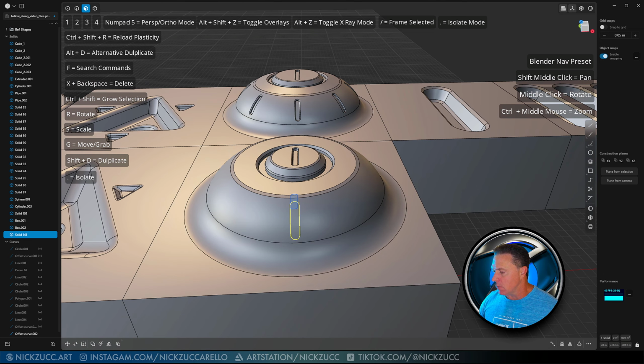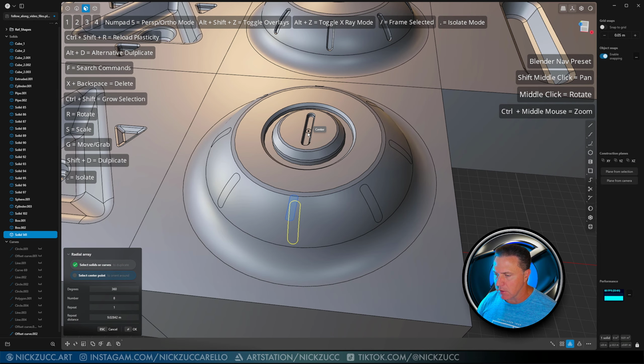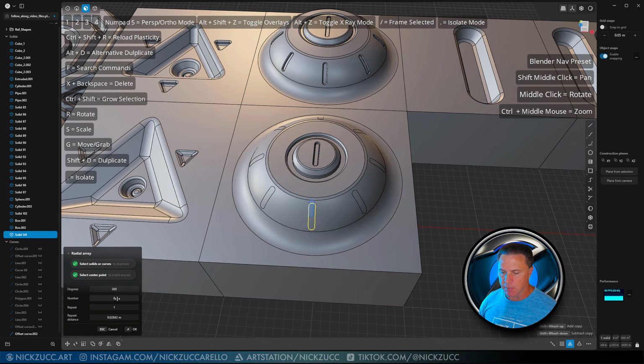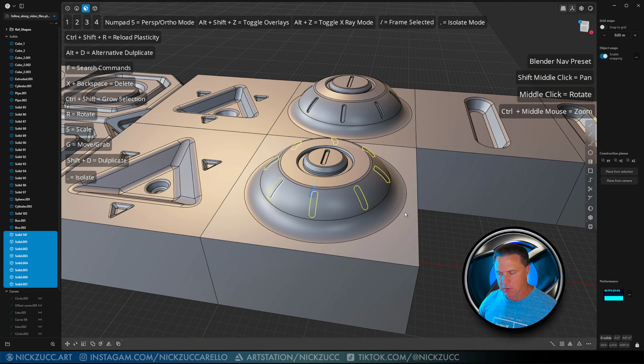Okay, so what I'm going to do is I created that shape. Now I can do the radial array. I'll go to the center of this right here like that, and depending on how many pieces you want, you could change the number to whatever it is that you want. I was going to go ahead and do 8 like we got here already. And it's already going to select this.